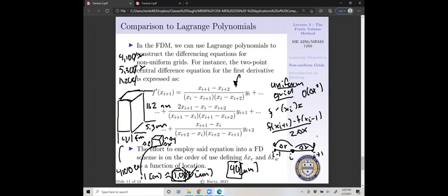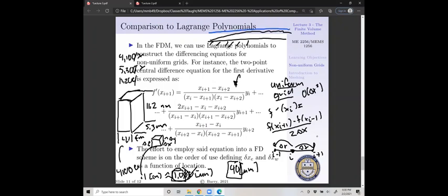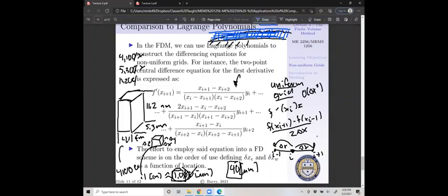Another thing that I would mention, though, is sometimes you do want high mesh resolution in areas where things are happening. For instance, fluid flow. So you've got a surface and you've got a boundary layer forming, and it breaks up. So typically what you do is a kind of power law. So you can pack in a huge bunch of mesh right in this boundary layer, because that's where you want to capture all the physics. That's where you're determining your drag. And then once you get into your free stream, you can start expanding it out quite a bit.